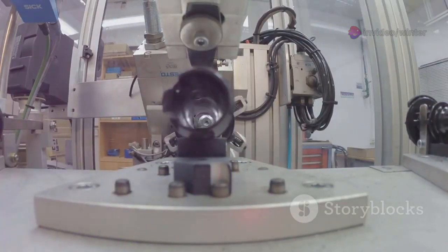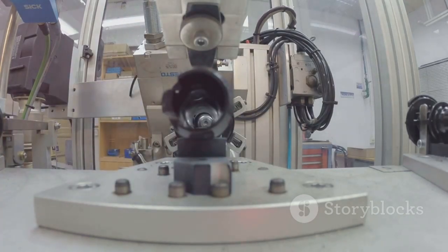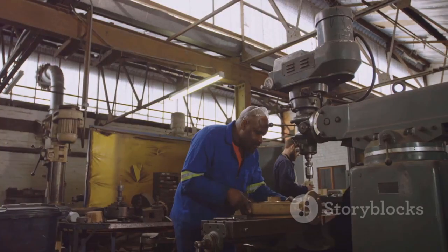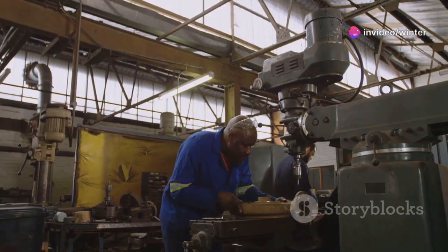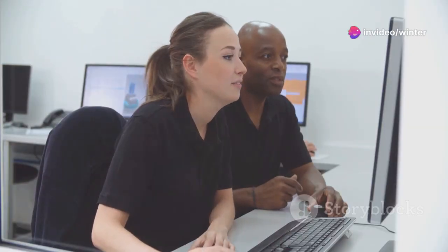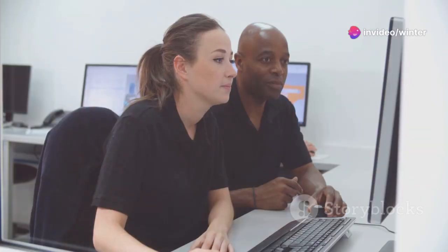Ejector pins, guide pillars, bushings, buy them standard, not custom. Designing for standard components means quick replacements and less downtime. Custom sizes require manual machining, adding cost with no benefit to your part. Even for part features, design for standard inserts and fasteners.